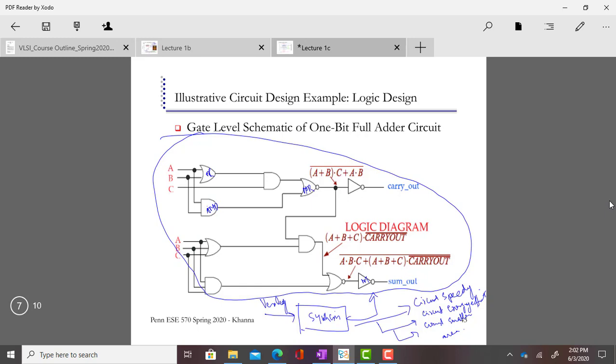But sometimes for very complex circuits you have to help the synthesizer. It may not be able to give you the perfect circuit because it is software, it is not intelligent. It is made to work for certain cases, and if those cases do not apply, then it will fail. For most users the synthesizer is good enough, but the advanced user has to help the synthesizer.